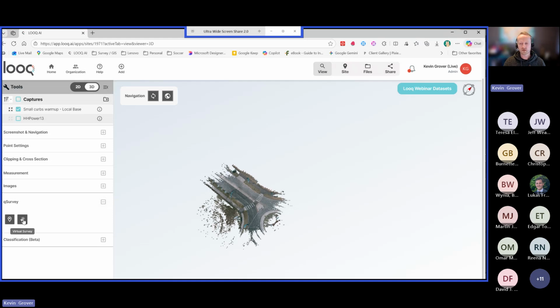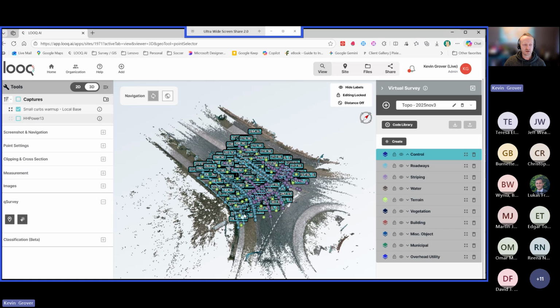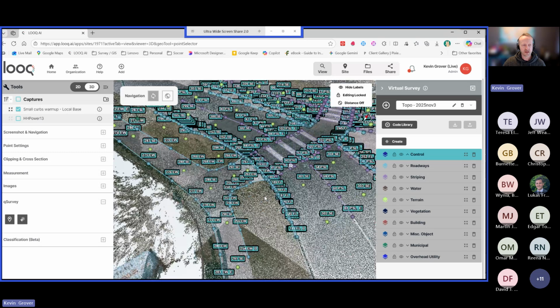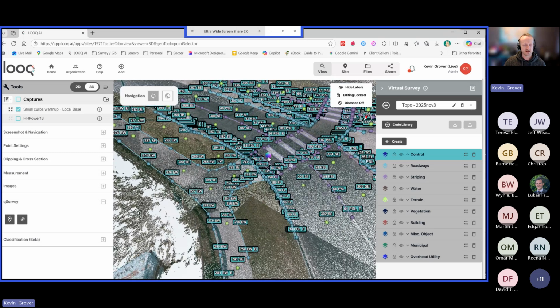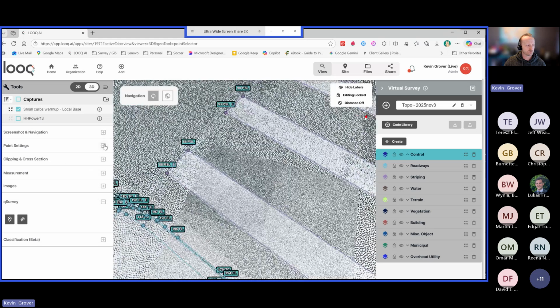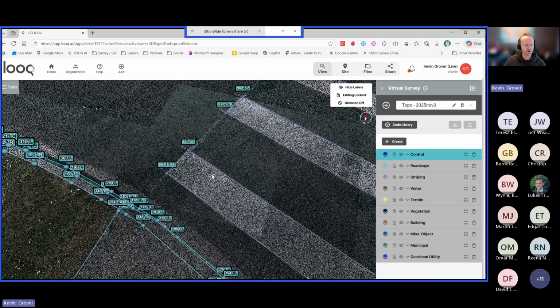So this is something where the point clouds are bigger files that are honestly challenging to work with in a Civil 3D environment. So we offer a tool even for virtual surveying, which allows you to basically create some survey point data and intelligence from our data that actually is quite easy to use within a Civil 3D environment. So typically for a very conventional survey, you'd go out into the field and you'd actually start surveying certain locations that are of interest to you within the data set.